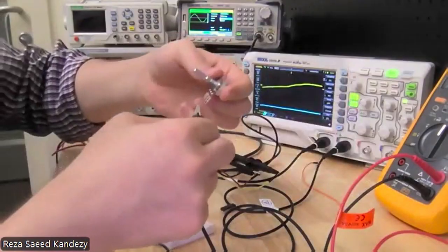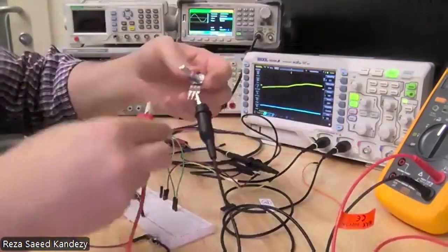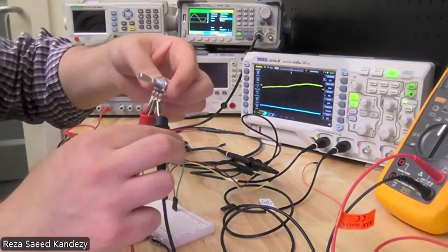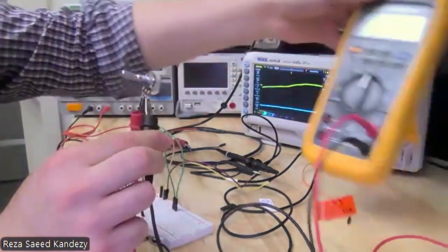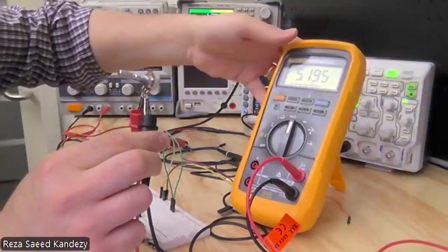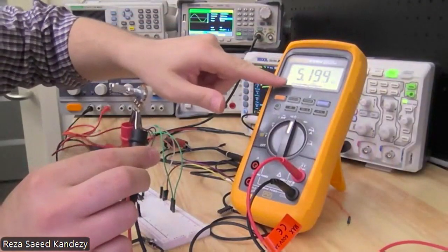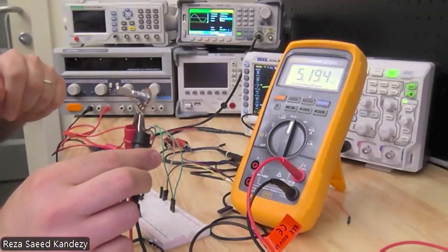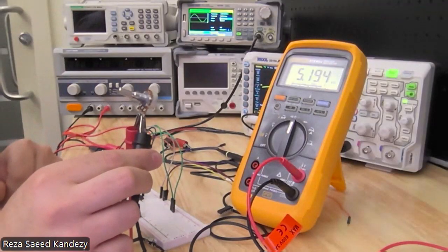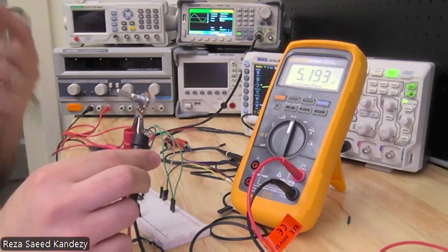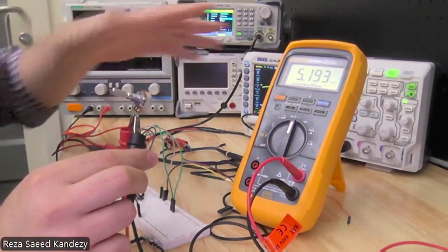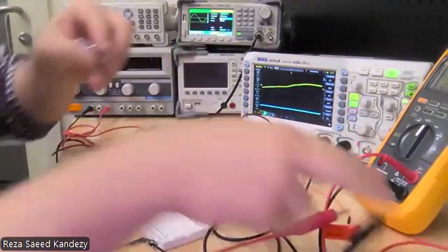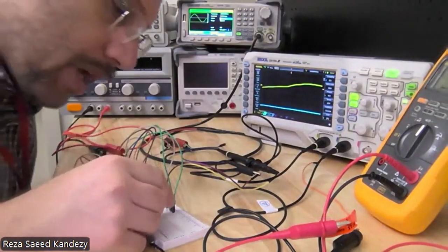Again, I am going to measure my beautiful potentiometer. The difference is a little bit more than I expected. Right now I am at 5.19 kilo, and it gave me that 40 gain. So right now you see how the potentiometer can adjust the gain in our voltage.